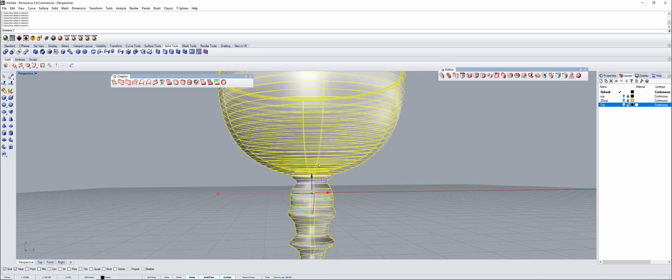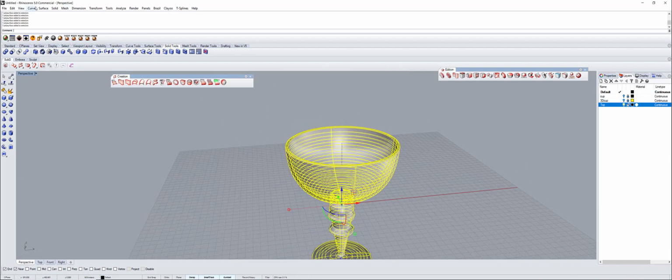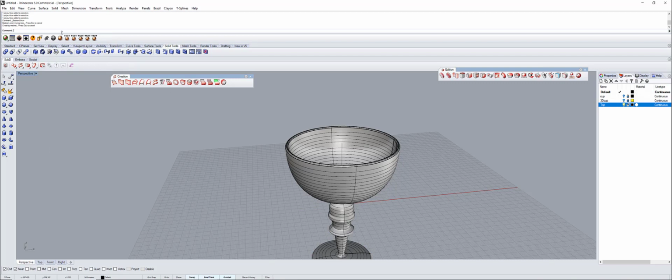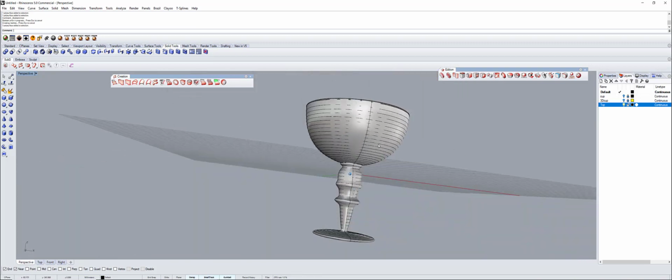So you click with shift the two parts, and we're gonna go to solid, and we're gonna go to union. So this is gonna be a union boolean. Union two, creating mesh, press K to cancel, union. Okay, so it's supposed to be one part right now. So let's click at it. Yeah, that's one part right now.